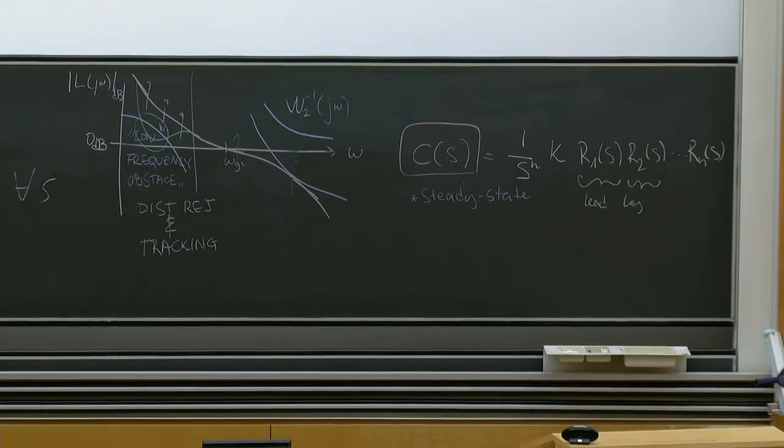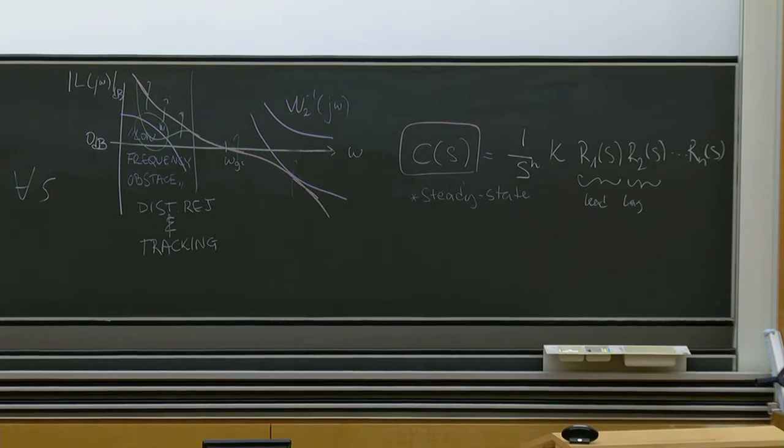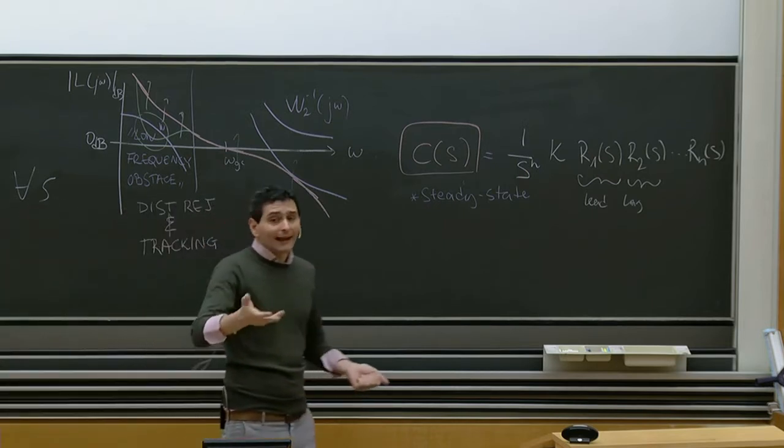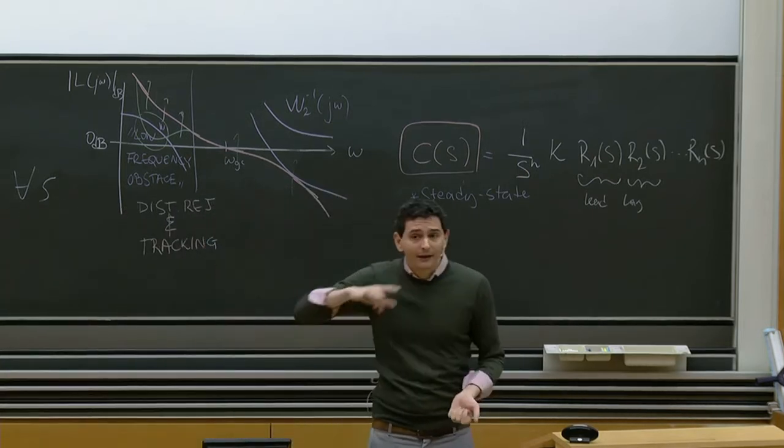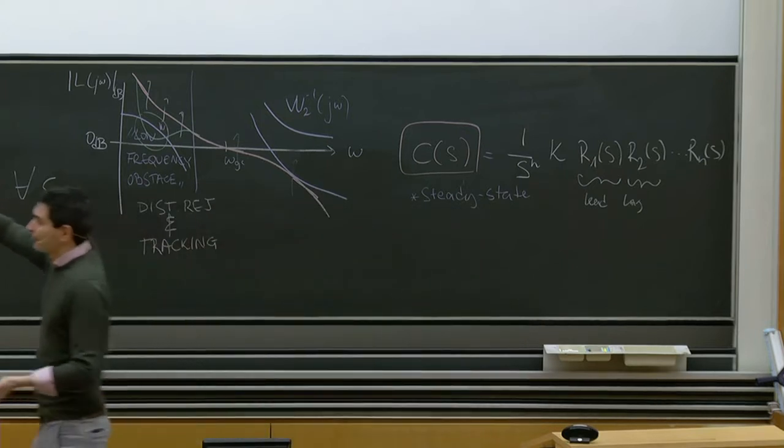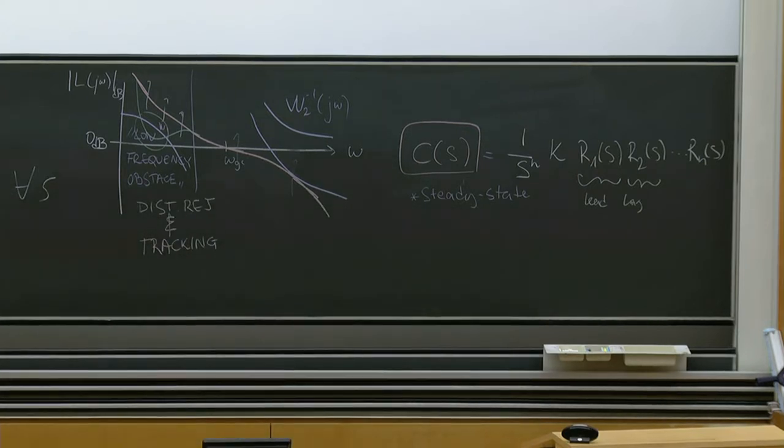You just have these three coefficients that you can play around with, and you pretty much know the proportional one will get you stability, the integral one will get you steady state errors satisfied, and the derivative one will make you get better time transient domain performances. And actually, you just need to feed back the y, right? So when you feed back the y, all you need to do, so what is the y?